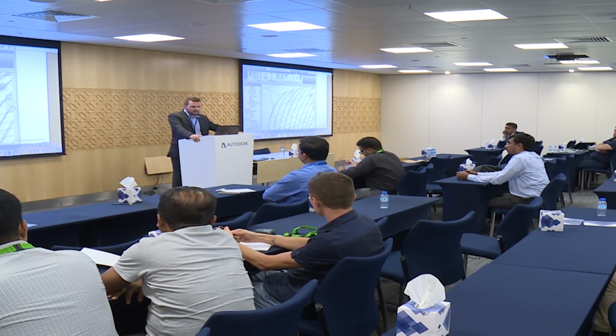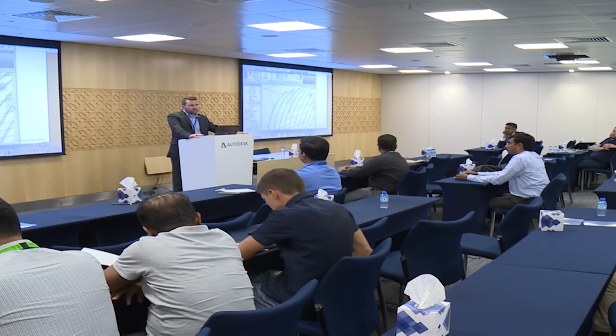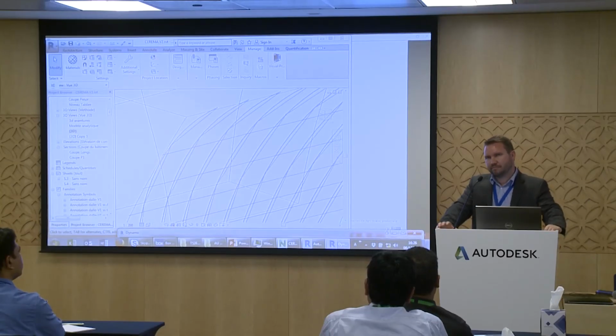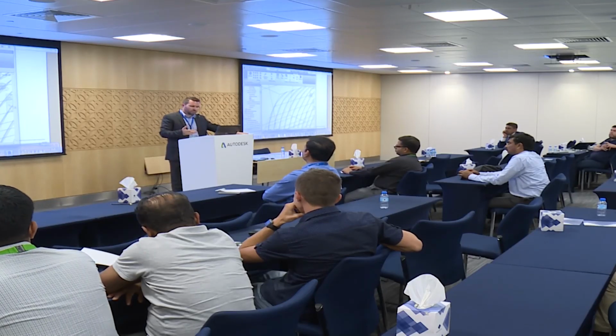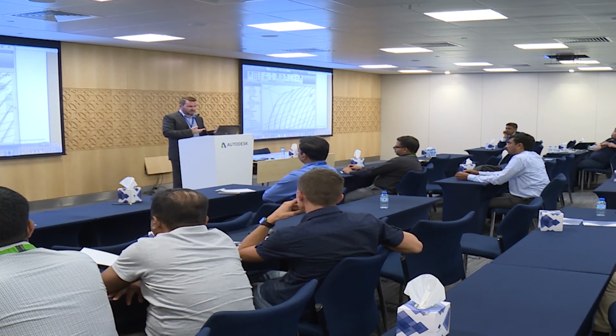For steel, now you can do some elements in Revit for plates, something like that. But at the end, if you want to really create the shop drawings, I think you will have some difficulties creating everything you want with Revit, so you have to use Advanced Steel at the end. And there is a bidirectional link. And for reinforcement, I think 3D is nice, but you have to create 2D views to explain how it will be created.